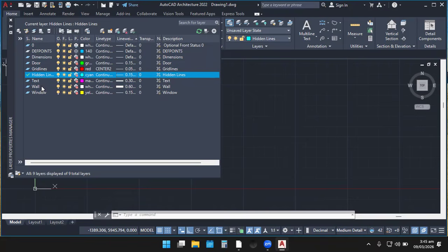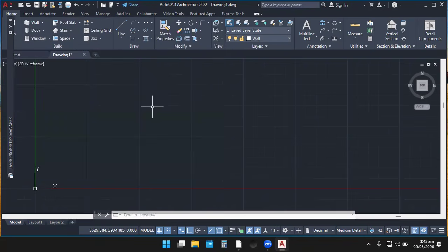So first of all, we want to start with the wall. So I click wall. I set the current layer. You understand? I come and click on auto hide. This menu over here, the first one is close, and this one is auto hide. This is the setting. Okay. So let's just hide it. Now let's proceed with our drawing.